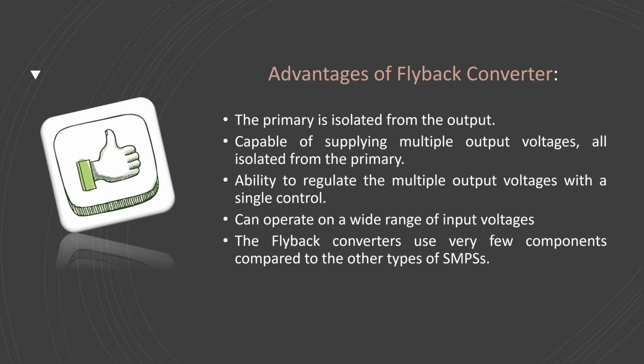What are the advantages of the flyback converter? The first advantage is the primary is isolated from the output. The second is it is capable of supplying multiple output voltages, all isolated from the primary. The third is the ability to regulate the multiple output voltages with a single control. The fourth is it can operate on a wide range of input voltage. Last but not least, the flyback converters use very few components compared to other types of SMPS.